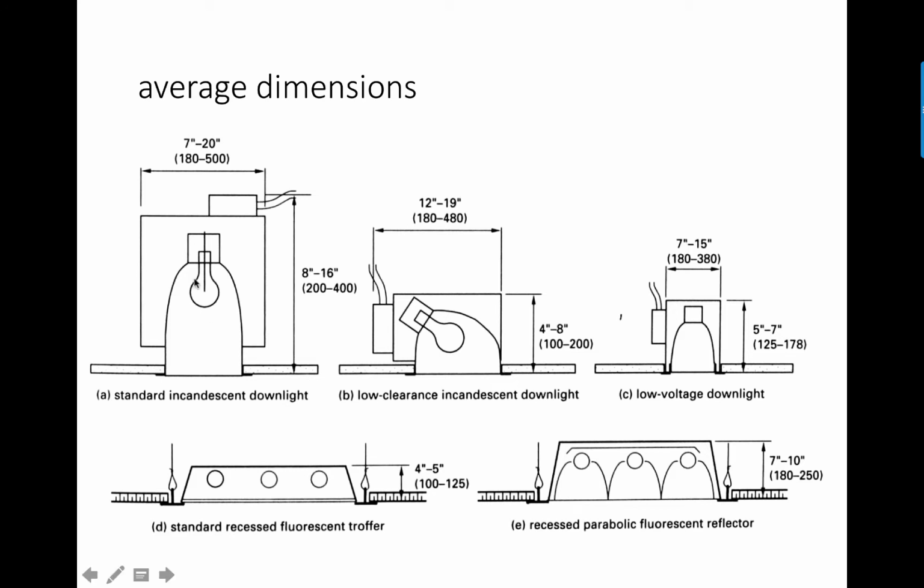But anyway, the other thing is that you have to consider the dimension of the light fixtures that you have in your ceiling and how that's going to impact ductwork. So, for example, if you have light fixtures that are 8 inches high, that's fine. That might squeeze into residential framing. But what if you need to get a duct above this? Well, a 12-inch duct above this makes it absolutely huge. So you need to be aware, like fluorescent lights can be pretty flat, but some incandescent lights can be quite tall. And even LED, if they're low glare, can be quite tall.